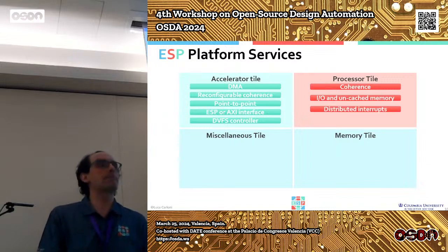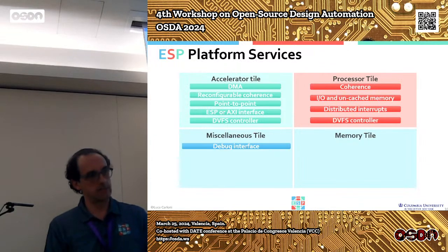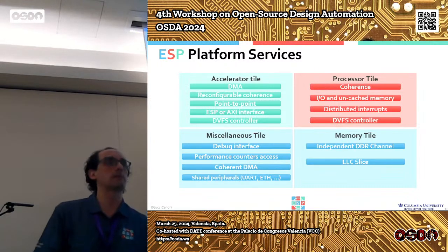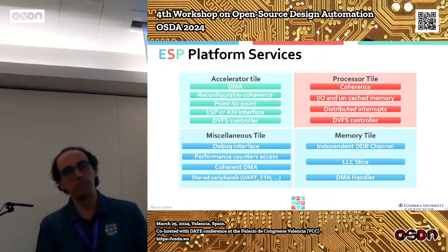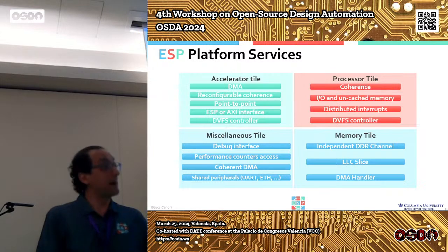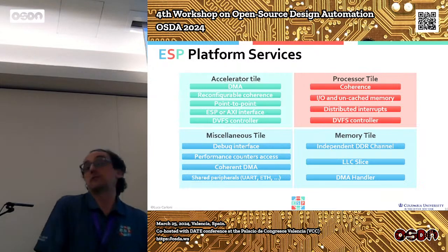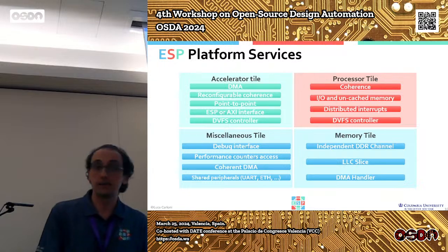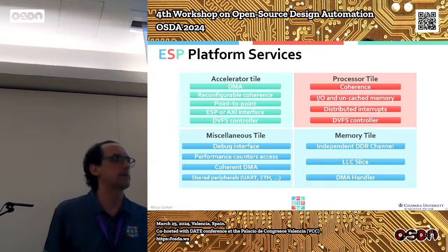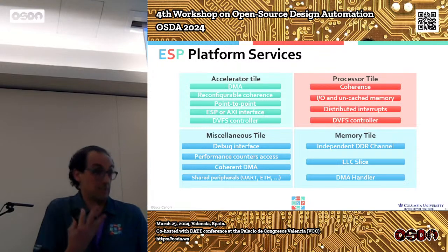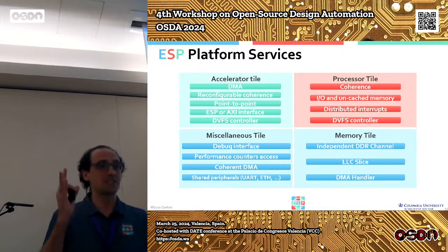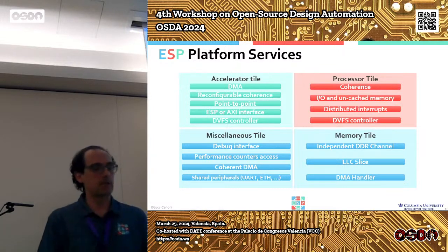You want to decouple the design of the component from the design of the system, and you want to make sure that certain problems that are very important in system integration, for example, managing coherency, supporting DMA, supporting interrupts, also lower level problems, like supporting dynamic voltage frequency scaling at the level of tiles, don't have to be reinvented all the time. You don't want to reinvent the wheel on this stuff. You want to focus on what is the key to innovation, which is which accelerator you design, which tile matrix you want to have in your system, which tiles, number, mix, and so forth.